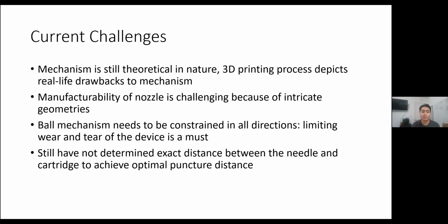without intent. And we're also still having issues determining the exact distance between the needle and the cartridge to achieve the optimal puncture distance, because the current springs we have are theoretically optimal for this application with the optimal puncturing force. However, theoretical is theoretical, and only through testing will we be able to really fully determine this distance between the needle and the cartridge. And with the 3D printing process, we're able to take steps towards that. However, it's still something we're working on, and I do believe that with this printing process, we'll be able to get a little closer to this.